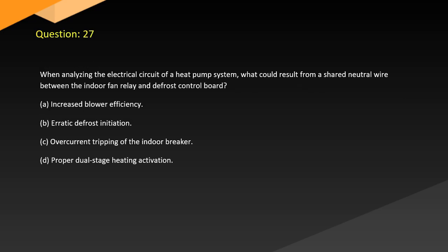Question 27. When analyzing the electrical circuit of a heat pump system, what could result from a shared neutral wire between the indoor fan relay and defrost control board? A. Increased blower efficiency. B. Erratic defrost initiation. C. Overcurrent tripping of the indoor breaker. D. Proper dual stage heating activation.